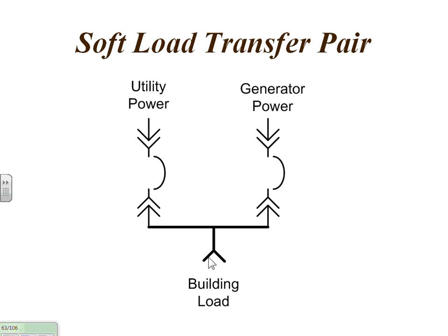Just normal operation. When the utility comes back, because it's electrically operated, we have controls that are going to say, well, no, you can't close. We'll synchronize the generator to the utility. And when they're in sync, we close the utility breaker, and load ramps off the generator back onto the utility electronically through a loading control, is what they call it.